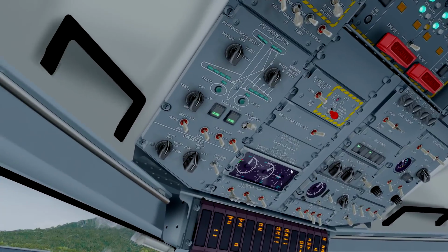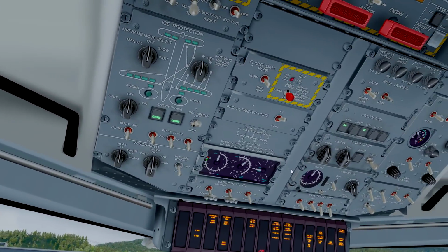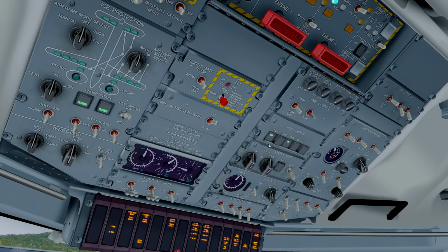If you want some air conditioning on board the airplane, you have to turn on the bleed air of the APU. And as you can hear in the background, it is indeed supplying bleed air. Now in order for the APU to properly provide bleed air, you have to make sure that the bleed air switches of the engines are turned off. If they're turned on, as you can hear, the bleed air stops. So you have to make sure that the bleeds of the engines are off if you want to let the APU provide some bleed air. Okay, so that's all set for now.